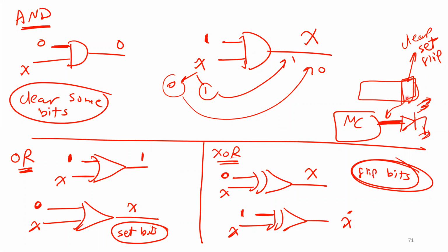Okay, guys? Same thing. If I want to put 5 volt here to turn it on, I have a byte and I have to put in number 1. Okay, AND cannot be used to set bits to 1; AND can only be used if you want to clear bits. Is that okay, guys? Okay. What about OR? Again, I'm going to explain how OR works, and you should figure out how OR can be used to manipulate bits.